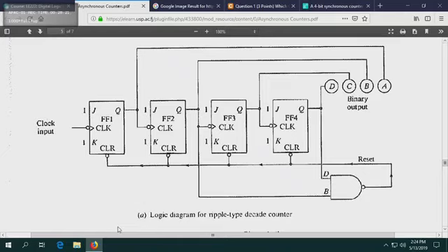The JK flip-flop. And how do you make the JK flip-flop toggle? You provide J equals 1, K equals 1. That's why you always see J equals 1, K equals 1. Can you see there's nothing going into the gates? There's no gate system going into J and K. If you look at your project, now you're so familiar with your project, J and K, the entry point was filled with a big gate system and OR system. Over here, no more.